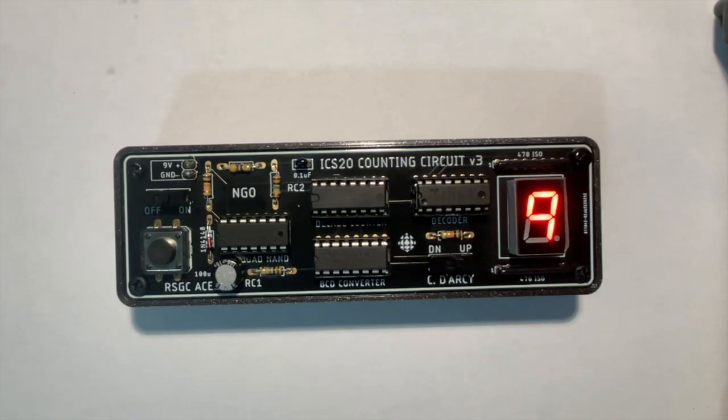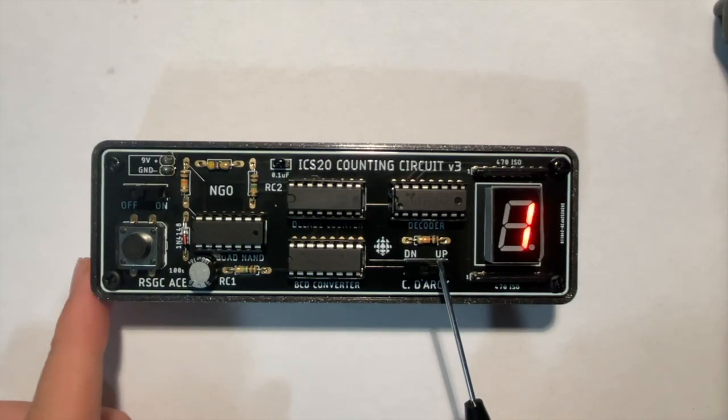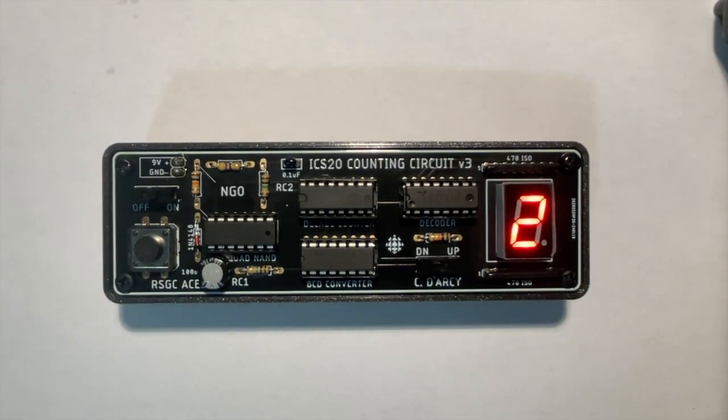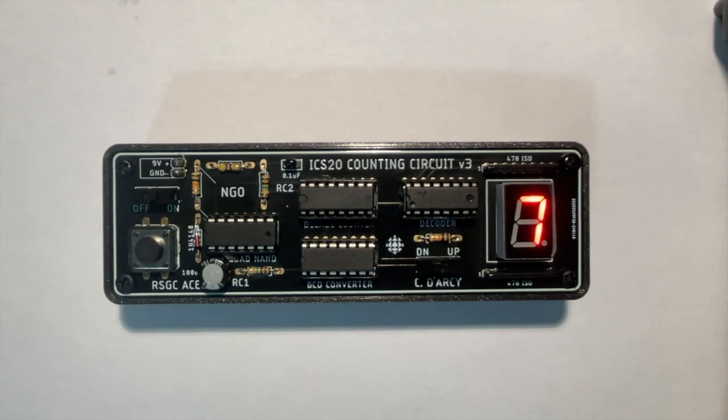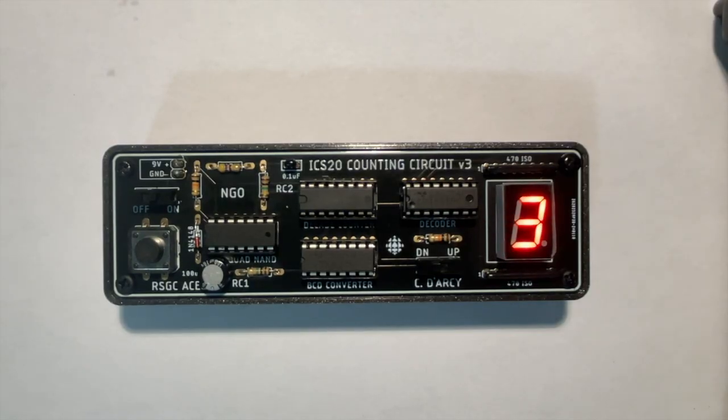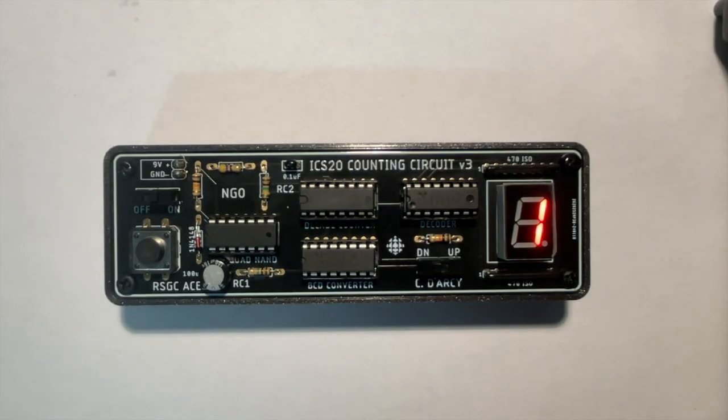Inputs like the push button, power switch, and mode switch are soldered directly to the board. The slide switch to control the numbers going forward or backwards in the count is also built in, allowing the direction to be changed using the 4510's up/down pin and clock input. One important change is the use of resistor networks instead of individual resistors. These compact components contain multiple resistors in one package and are mainly used for the 7-segment display.